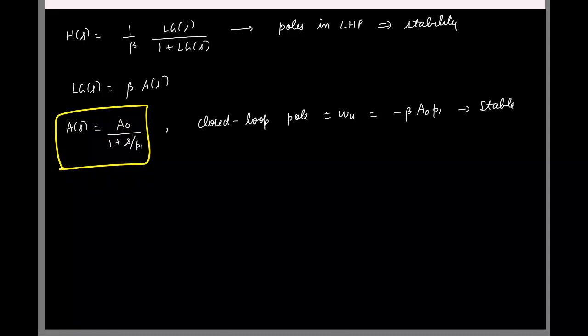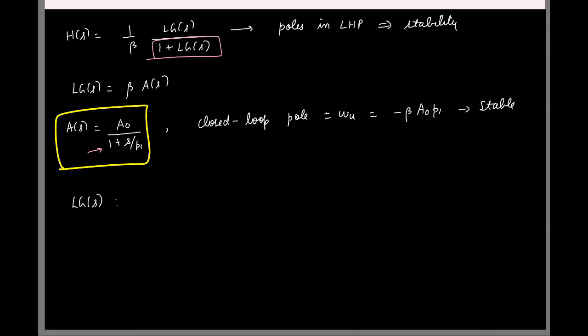So of course, if I have a simple first order system, I can do this and find out approximate as, so if you have a simple system like this, you can find out the closed loop pole, but of course in practice you will have a higher order system. So obviously it's not practical to find the pole locations of this guy and make comments on stability. So it might be better if you can look at just the loop gain and make any conclusions about the stability of the closed loop system. So do you guys know some techniques which can help you say that?